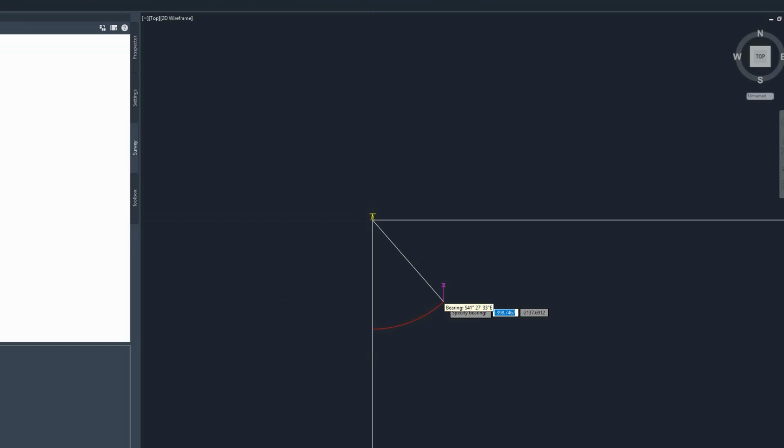And this is an important thing to know here. It's an error in Civil 3D's actual description. It says spaced, but that is not what we're going to be doing. What we would do is, the degrees is the whole number. Then it would be a decimal point for the minutes. The next two, the tenths and hundredths place, are going to be your minutes. And then anything after that is your seconds. So I went ahead and just put in 42.0000 to show you that. If you try to do spaces, it moves directly on from your bearing to your distance.